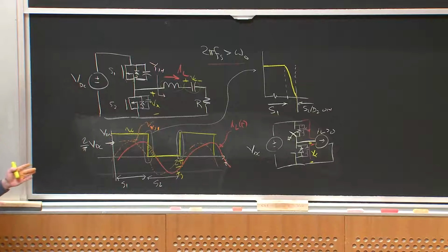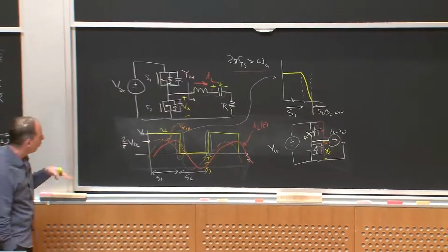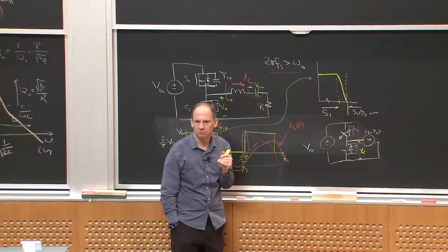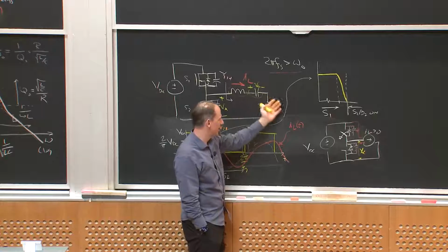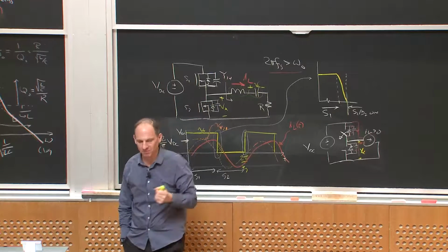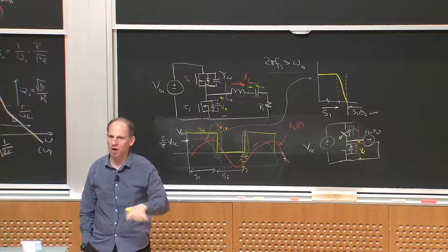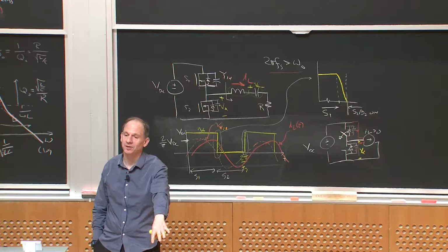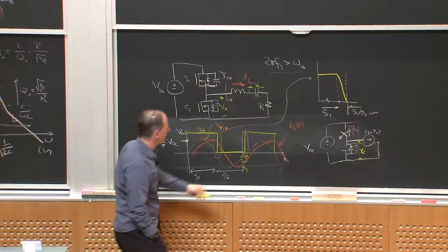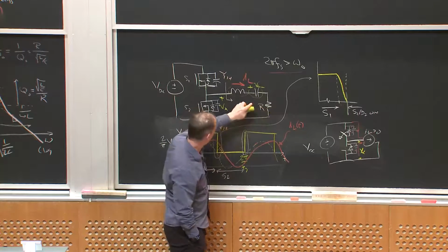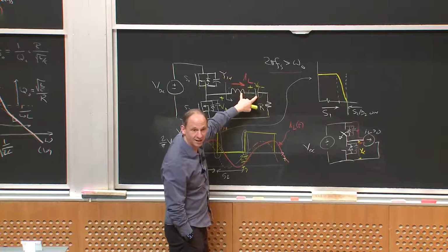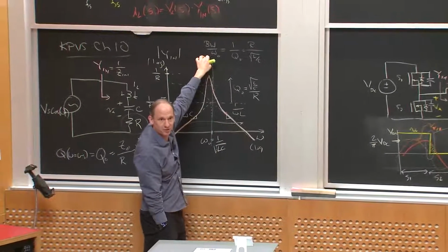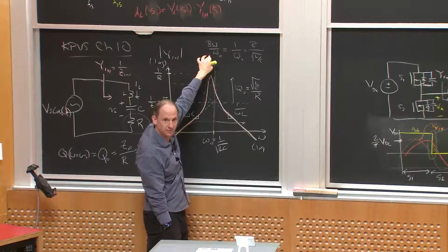But here's a challenge. Suppose now I don't control this resistor very well. If this was an induction heater, the equivalent resistance I might see might depend upon the thing I've put on my network to heat, right? How much energy I'm going to dump into it. If this resistor gets too small, the quality factor of the network gets really high, and then I better stay away from resonance, otherwise I'll get huge voltages on my components, on my inductor and capacitor, okay?